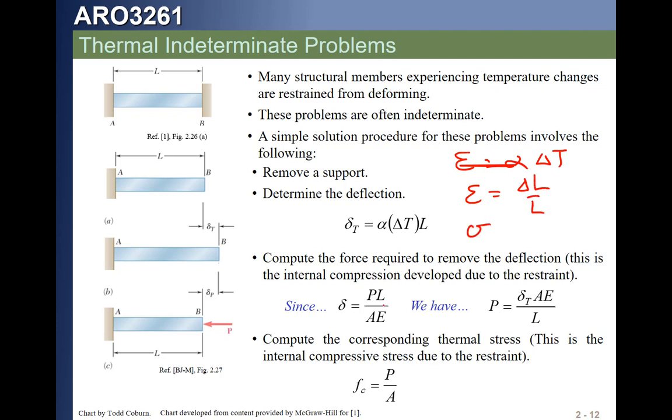The stress, though, for forces, is E, the modulus, times the strain. But if that piece we saw last slide is sitting on a frictionless surface and we apply a delta T, it gets larger, but because nothing constrains it, it develops no force.